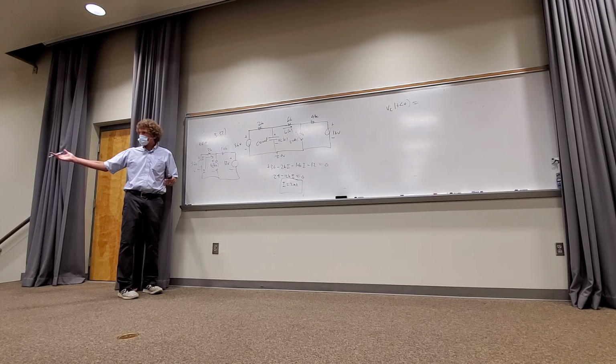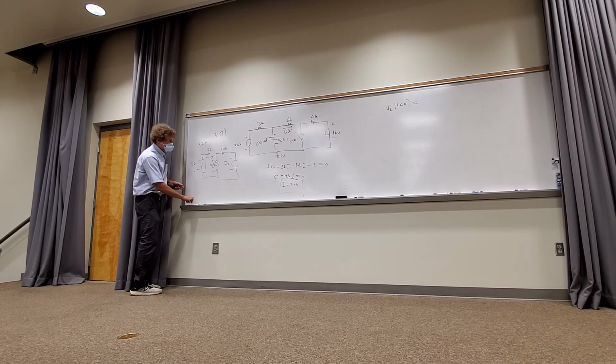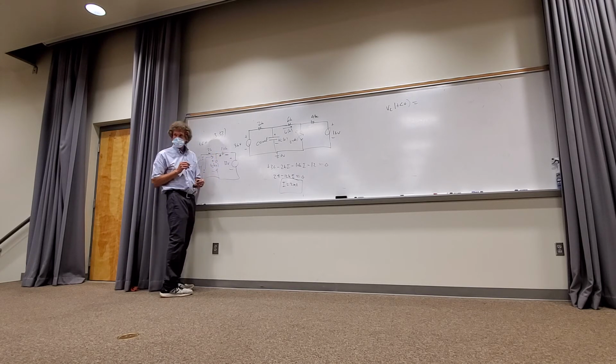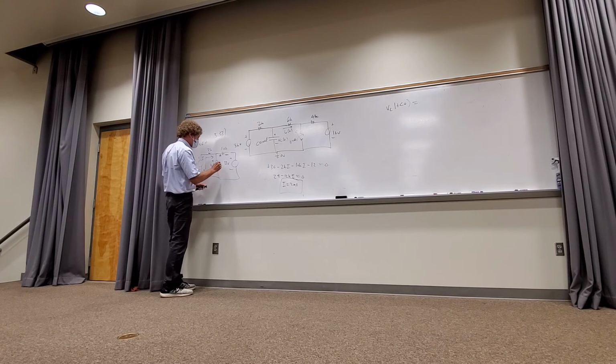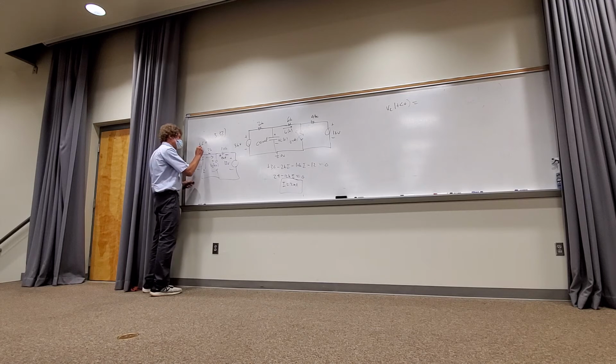Maybe you are right. Maybe it is easier. But if I have that as 2 milliamps, right? Don't I know the voltage here? Isn't that 20 volts, class? 2 milliamps times 10K would be 20 volts. Do you agree? Right? So that's 20 volts, right? What about this? 2 milliamps, 2K is 4 volts, isn't it? So this is plus to minus 4 volts.